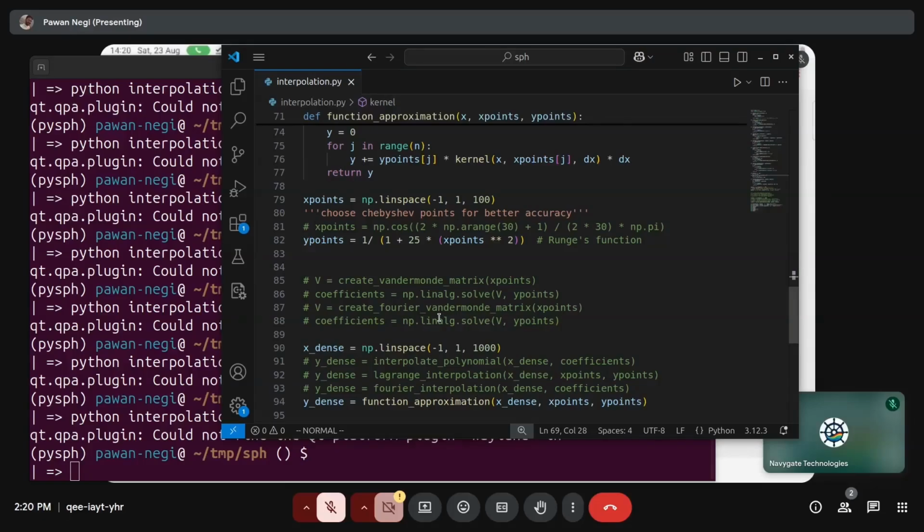And then we'll solve one problem using the SPH method, and then we will talk about PySPH software, which is an open source software, and that provides a framework that you can use to simulate very involved phenomena, for example a dam break or multi-phase flows, by writing equations in a certain format which are very easy. And if you understand SPH, then you can easily write those equations and solve any kind of phenomenon.